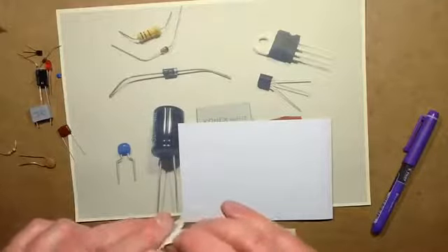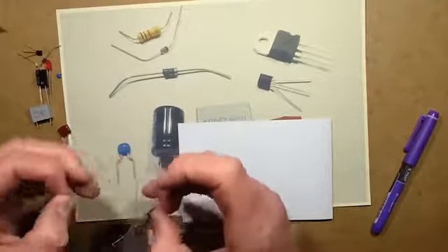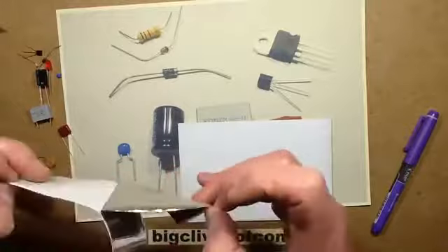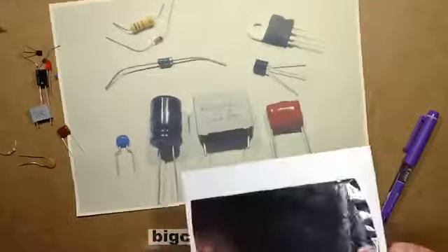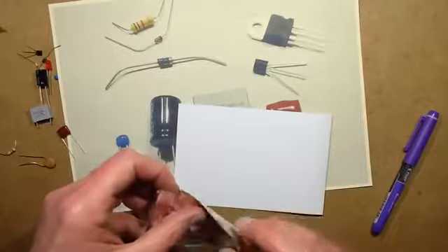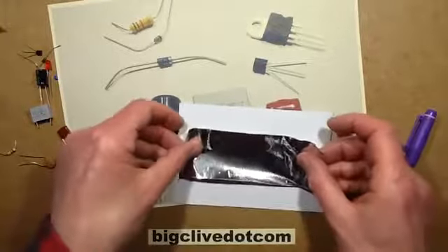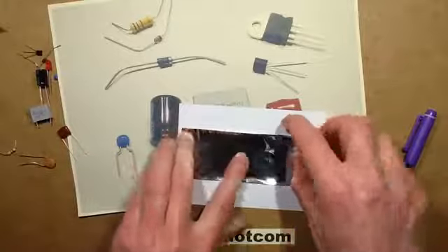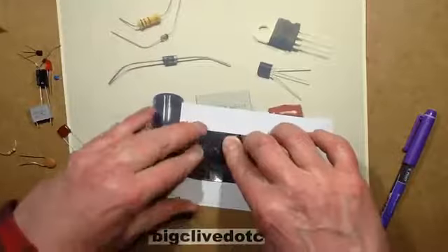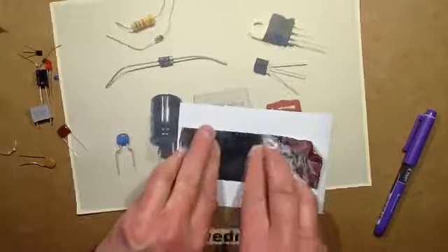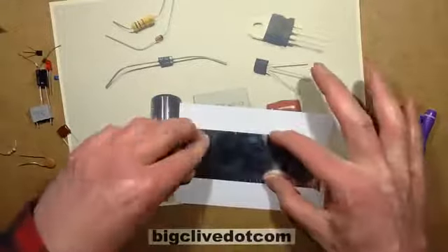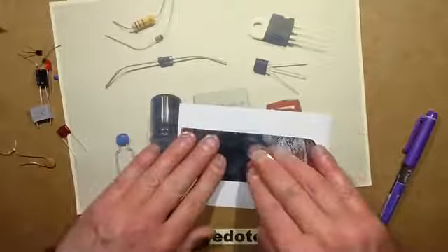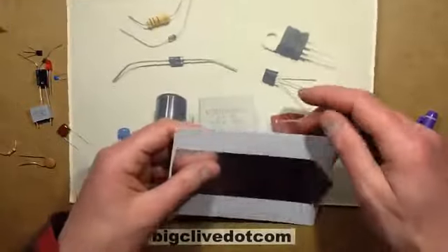And this is the physical construction that's used throughout all capacitors. They're all pretty much like this, but not using cardboard and aluminium foil. So let's get that as close to the other one in alignment as possible. And the 2 factors determining the capacitance here are the area of metallization that's in parallel with the other one, and how thick the insulator is in between.